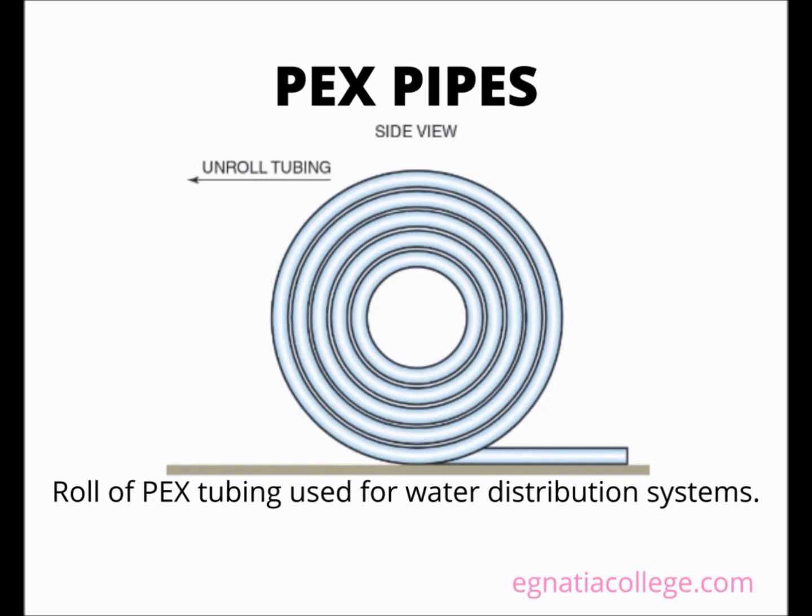Plastic tubing should be handled with more care than rigid pipe or copper tube. Scratching the side of the tubing when installing it through drilled holes can shorten the life of the product. Nails that protrude in a drilled hole where the tubing is inserted can gouge the PEX tubing.